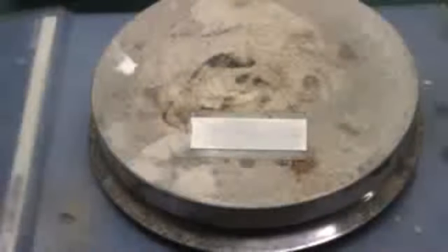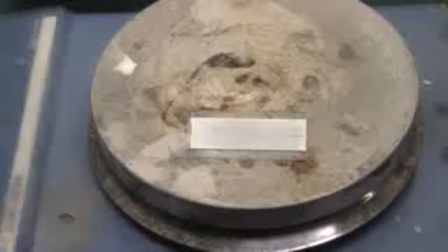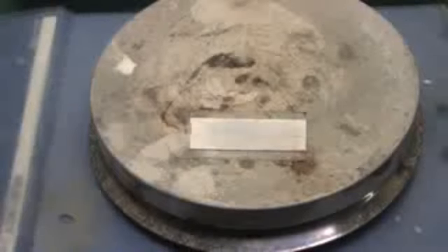Now simply let it dry for several minutes. When that's done, carefully peel away the tape and clean off any titanium dioxide that might have oozed around the back. Now place it onto a hot plate and heat it to at least 300 Celsius, preferably higher. The titanium dioxide will turn yellow at first as the organic detergent is decomposing. Keep heating it until it whitens again and fuses the titanium dioxide to the glass so it'll stick even when we add water later. In total, this takes about 20 minutes.